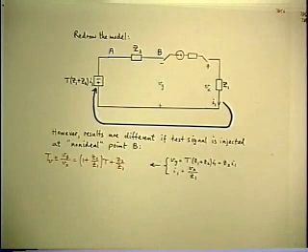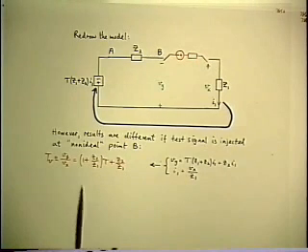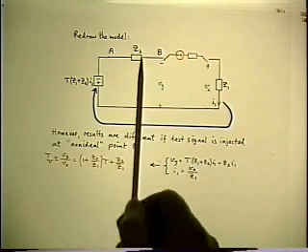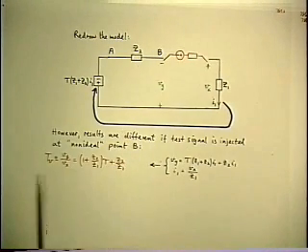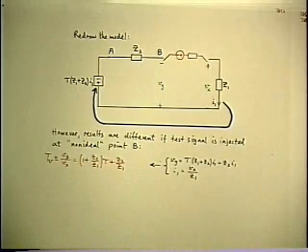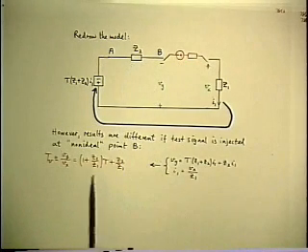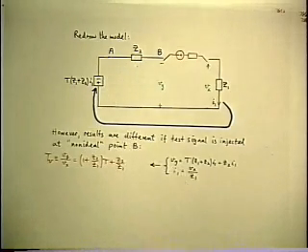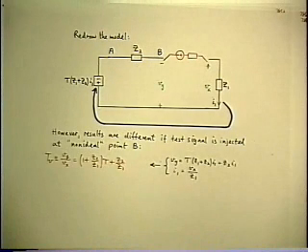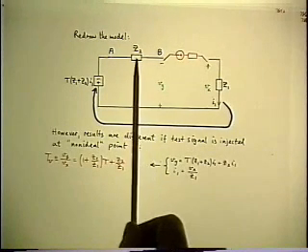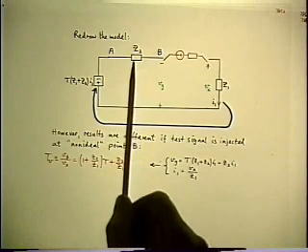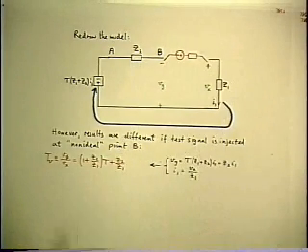But it's certainly worthwhile doing this, because now we know what it is we do get. And obviously, if Z2 goes to 0, then it reduces to the right answer because you're reducing it back to the ideal case again. But if it's not ideal, it tells you how small the Z2 has to be in order to get close enough to the right answer. And the first thing you notice is it's not the absolute value that matters, although you could have guessed that anyway. It's the ratio of Z2 to Z1 that matters,